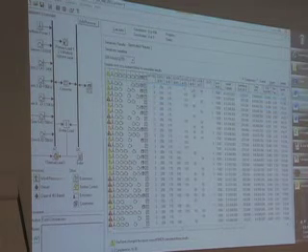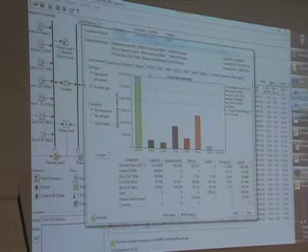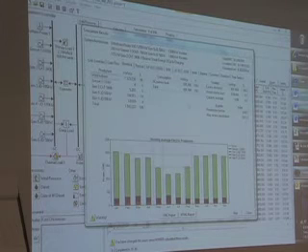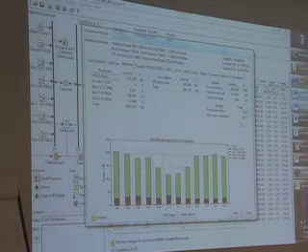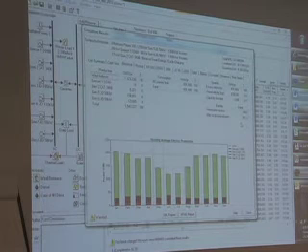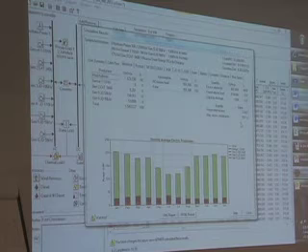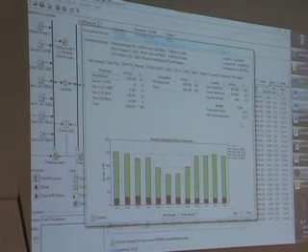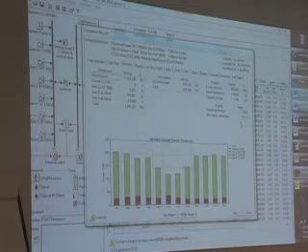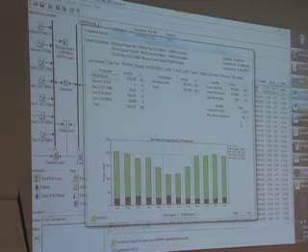If you come in here and look on the electrical tab, it's showing, now the guy from Power Corp said, how do you have more than 100% renewable penetration? Well, it depends how you define. This is instantaneous penetration, and I liked Steve's definition, which is in that time step, the renewable production divided by the load, the primary load in that time step.